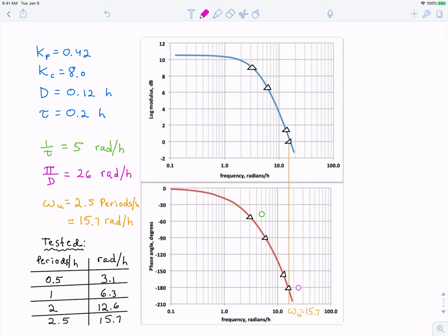Bode diagrams are one of the classic tools for control system analysis and design. While they have increasingly had to give way to direct dynamic simulations, they're still excellent tools to anticipate and predict what a control loop will do based on open loop information alone. In this video, I hope to have shown why too much gain in a control loop can cause self-oscillation and instability. The dynamic simulation to do so was arranged in an open loop fashion using 2 tanks. The simulated response of tank 2's temperature from a controller acting on a disturbance in tank 1 is nicely reflected by the open loop Bode plot of the system.